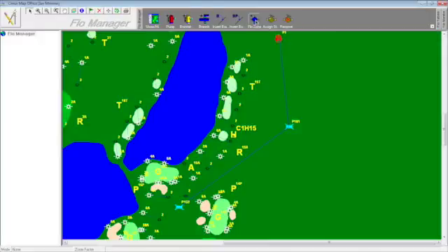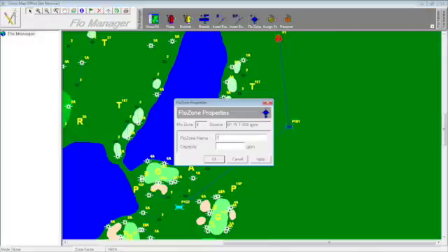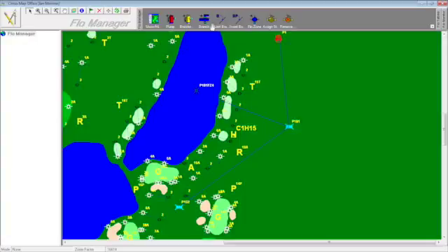Our next step is to add the flow zone to the given branches to assign sprinklers to specific stations on the map. Make sure to add the flow zone to the correct size of pipe. This is found on the pipe layout map for the course.